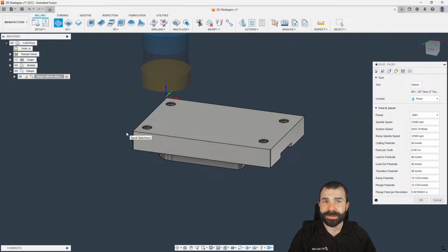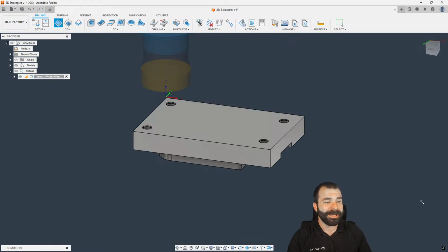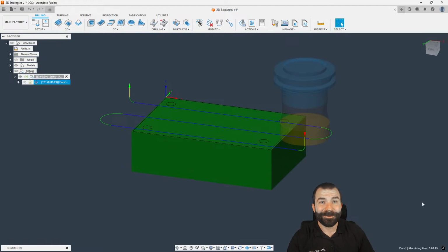So this is where you start to see the power of Fusion. And this is where I say the number one thing that I recommend to everybody. Because when I get support tickets at the end of the day, it absolutely makes me laugh. Because you're going to tell me that your toolpath doesn't work. I'm going to come in and, as you guys just saw me do, give it a tool and hit OK. And usually the toolpath is going to work. I don't know what happens. It's like your car at the mechanic. You take the car in and magically now it doesn't make that noise, right? This happens all the time when nobody blames anybody. Maybe I'm just a lucky guy in Fusion toolpaths. That said, when you're working in Fusion and you do run into some major problems, a lot of times just starting over on that toolpath will fix that.